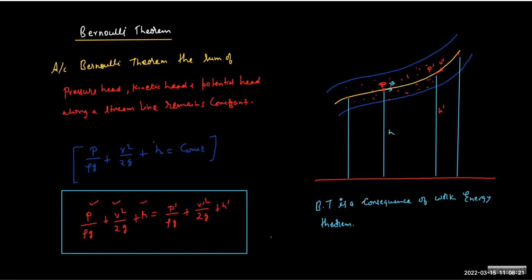It means when the liquid is in motion through a tube, because of the assumption that it's inviscid, the viscous drag or friction is assumed to be absent, and because the drag force is absent, there is absolutely no loss of energy.